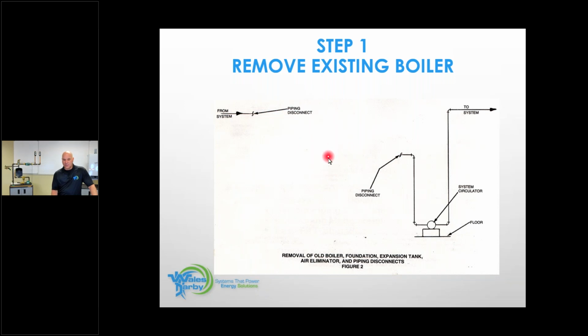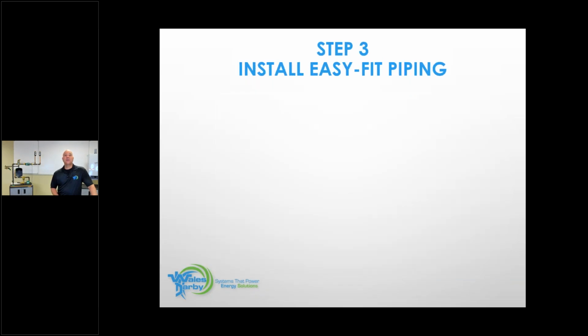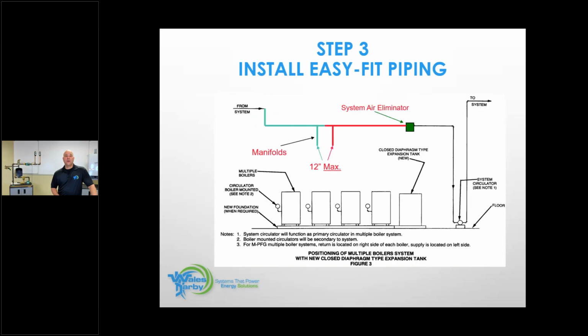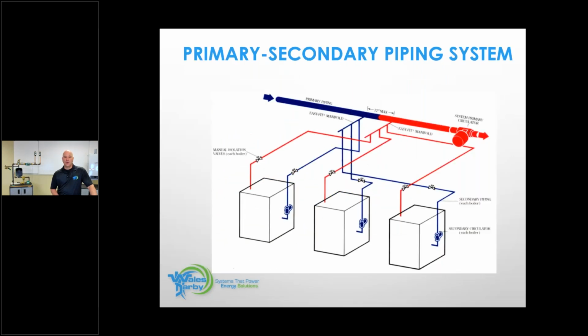Somewhere I'm going to take two closely spaced T's and make them 4 pipe diameters apart. And then I'm going to come out with a header and tie in my multiple boilers. So this is what it would look like. I tied them together. And this has a max of 12. That's going to be dictated by the pipe size. But if you keep 4 pipe diameters, outside dimension of these two T's, come off with the equal size header as this piping right here, you're going to be able to tie these boilers directly into those headers and create a multiple boiler type application.